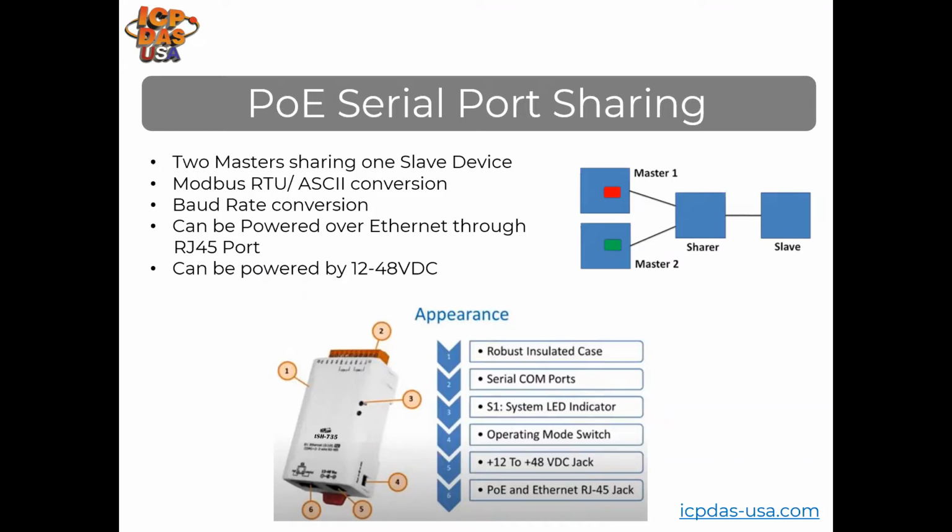Port sharing devices allow you to share physical COM ports among several applications. Once the COM port is shared, it can be opened by those applications at the same time. Modbus RTU is an open serial protocol derived from the master-slave architecture that's reliable and easy to use. With Modbus RTU on RS-485, you can only have one master. Serial port sharing devices like our TSH-700 series allow two Modbus masters to access the same slave device at the same time and are configurable over a web page.